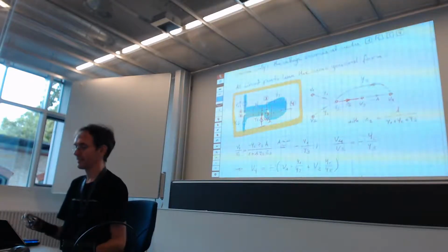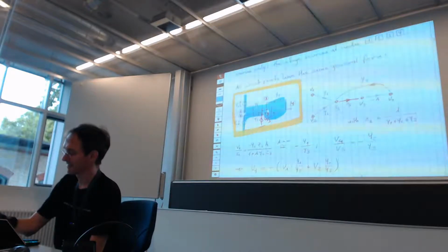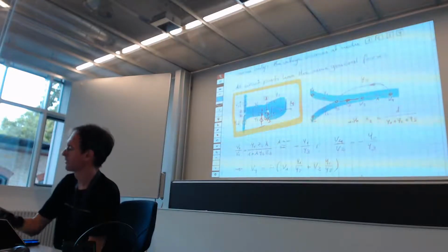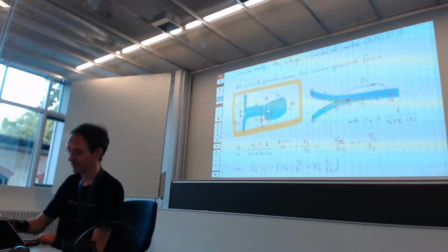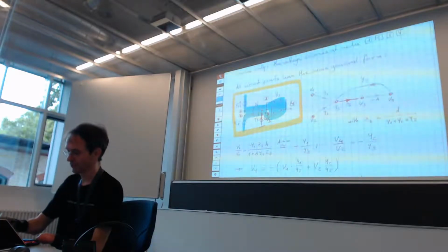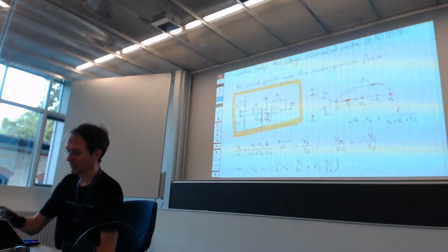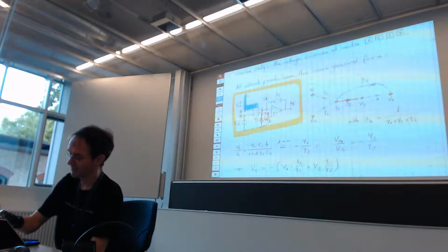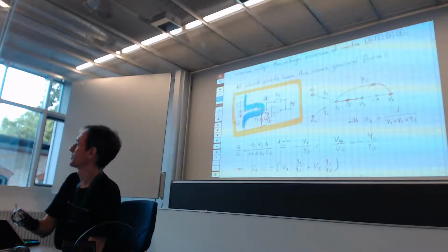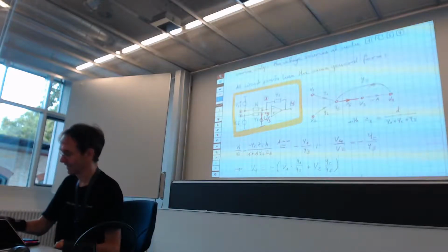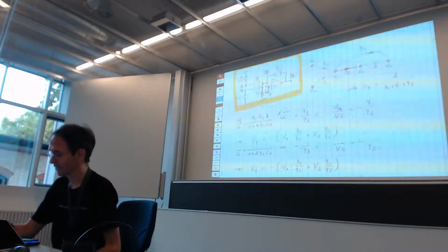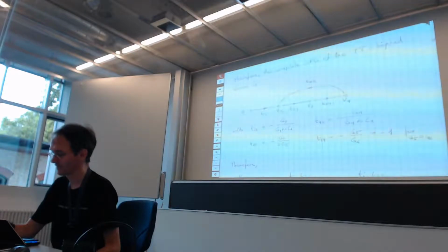And we have established with this analysis that from one node you will have a transfer to the output and from the other node you will have a transfer to the output. It is not possible for an op-amp circuit that you have a transfer from this to the input, is it? But that's what you just asked for, essentially, when you said, why does it not go in the signal flow graph here?